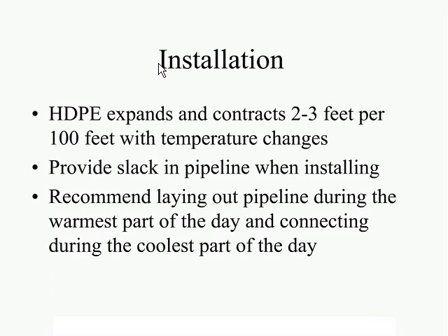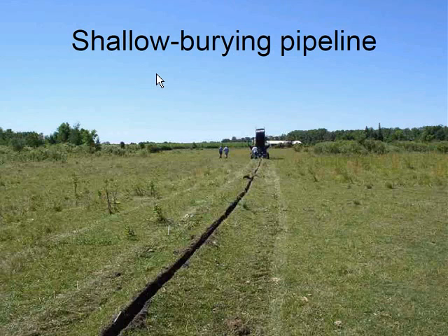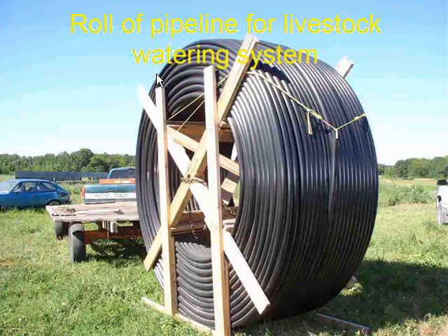Why does that matter? Well, you don't want to install the pipe in the heat of the day, and then when it gets cold, the pipe contracts and it's going to pop your connections. So we typically recommend laying out the pipe during the warmest part of the day and then connecting it in the coolest part of the day. And here's your pipe again. Shallow burial, there are tools out there. There are ditch witches or other tools that are used for burying pipeline. And the HDPE does come in rolls of pipe.